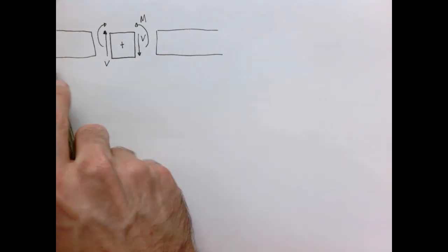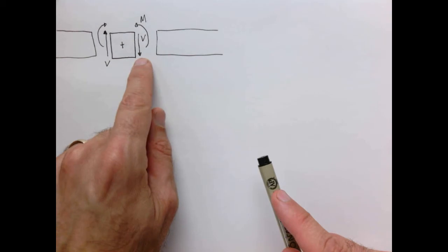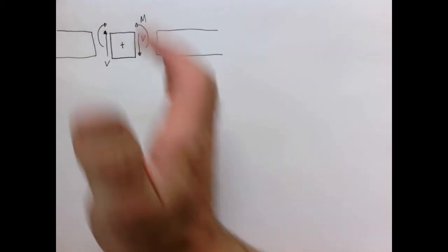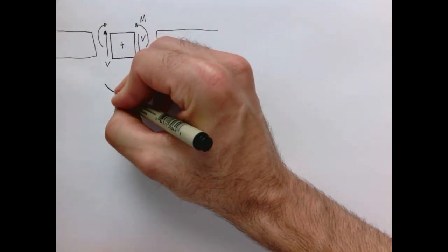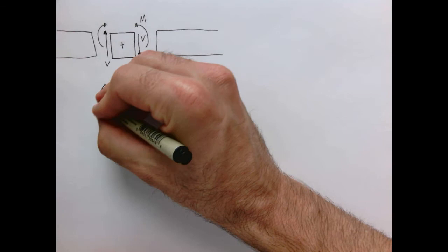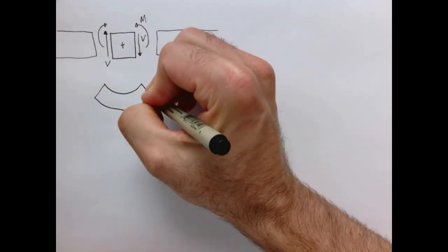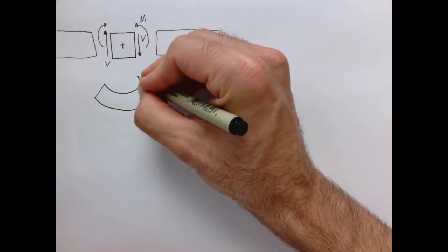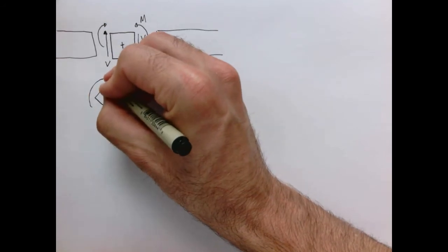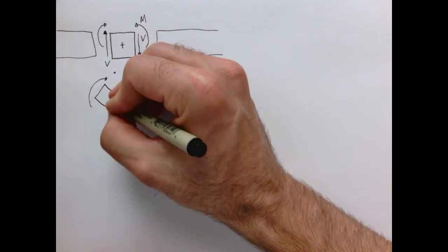So if we work from the left like we did in the last one, the downward shear is what we call positive, and the moment, which is turning this way, is upwards. So the way I always remember the moment is because if you imagine the moment, what it wants to do to the beam when it's positive is bend it upwards. And since it's positive, it's like a little happy face, right? So it wants to bend it upwards to smile.